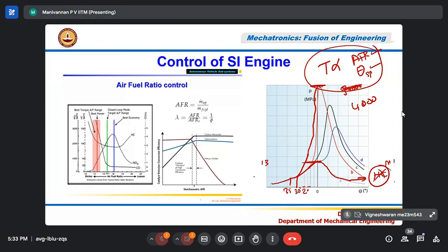Sir, it's basically about extracting the most combustion and the most thrust on the cylinder head, right? Yes, that's correct. So you want to see that the best combustion happens, all the fuel is burned, so no fuel comes out as HC emission, correct? And so that maximum torque is produced, you will get maximum fuel efficiency.